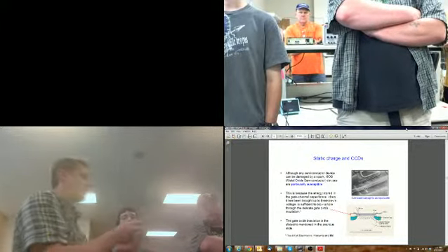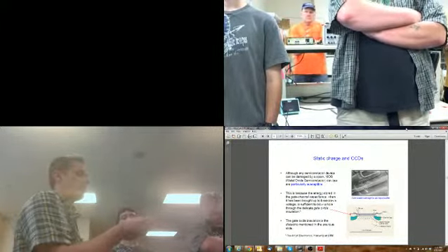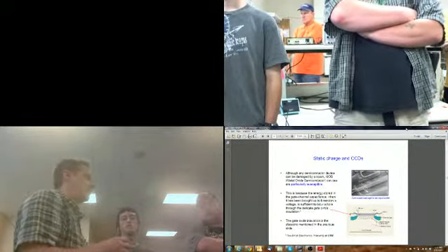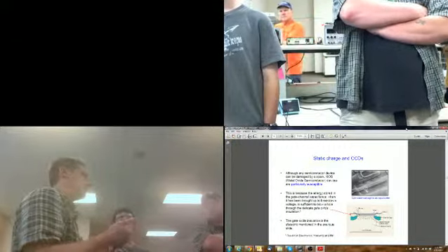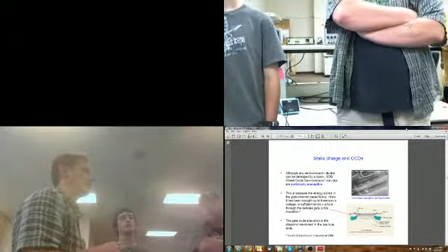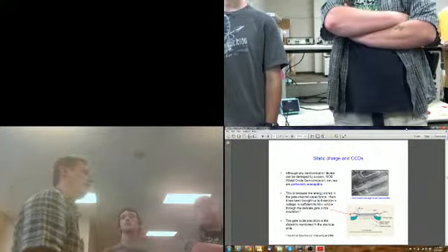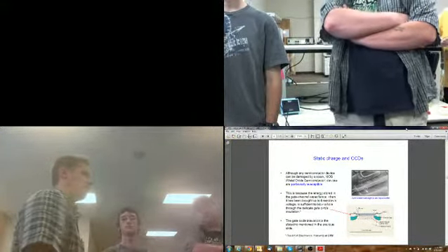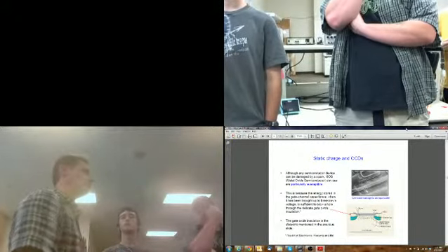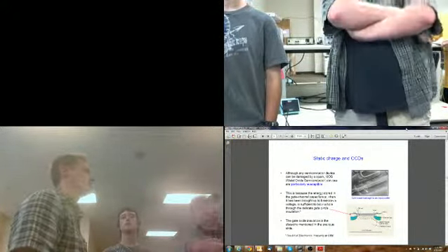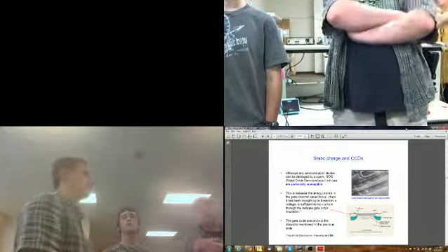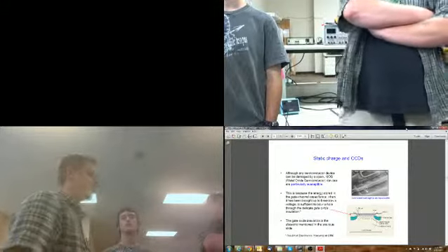So it's perfectly possible this chip could be blown, it could be damaged, it could be weakened. It's not always a catastrophic fault. Sometimes it's a degradation in performance. They've actually shown that you can take an analog op amp, for example, move around, shock it. It'll still work, but with reduced performance. So it creates higher resistance in the circuit? Yeah, like the output impedance would be increased, the input impedance would be increased. Long-term reliability would be reduced.